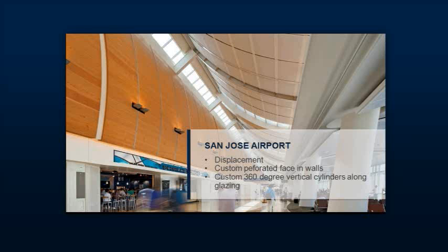The image you see here is Legacy High School. It's the last displacement job I'm going to discuss, pure displacement. Now this is, I believe, a radiant slab floor again. But you see that in between these window bays, you have these vertical boxes. Those are actually the displacement diffusers with a perforated face on them. You can see the supply duct being fed from above.